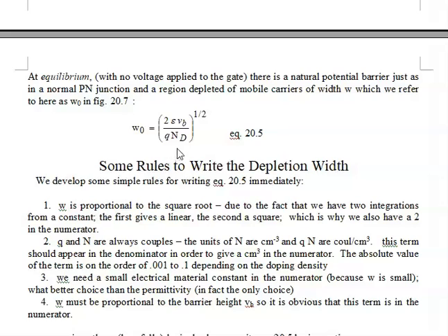We'd like to have those on the bottom because the units of ND are centimeters to the -3, so we bring up centimeters to the +3 on top, which is close to what we want. So we're figuring we probably have something divided by centimeters to get that to be centimeters squared. The units of voltage are, well, again, they're volts. It couldn't be easier than that. So the only thing we have to worry about are the units of permittivity. Well, we can do this now by sight. Permittivity has to be on top. Why?